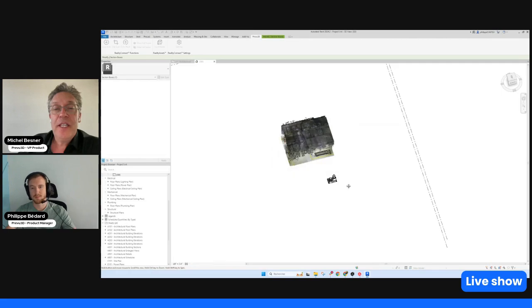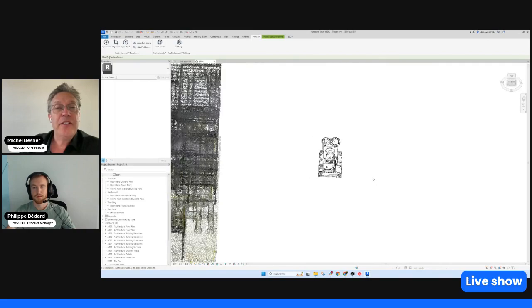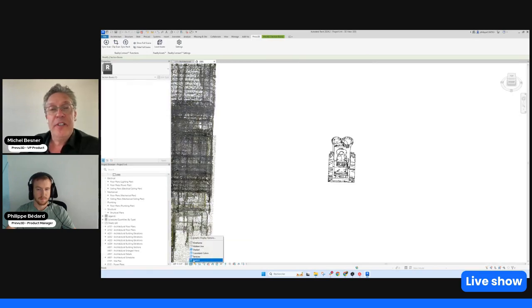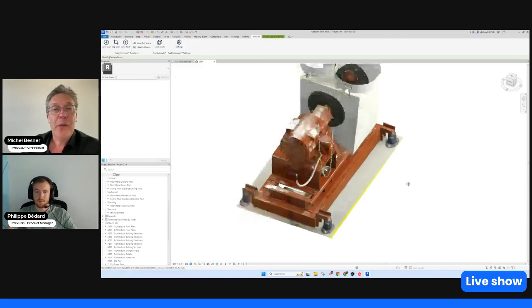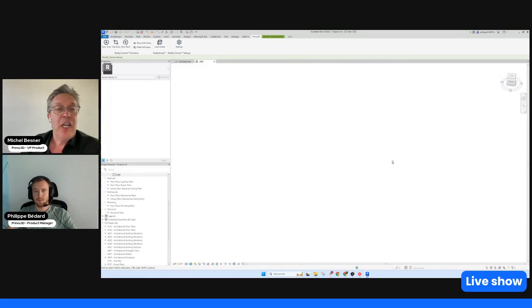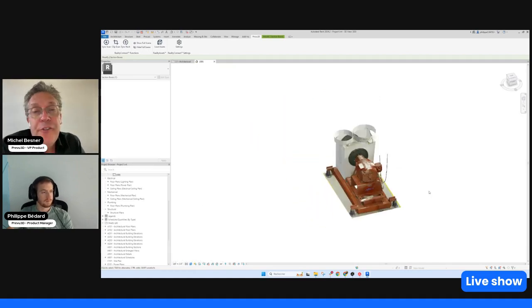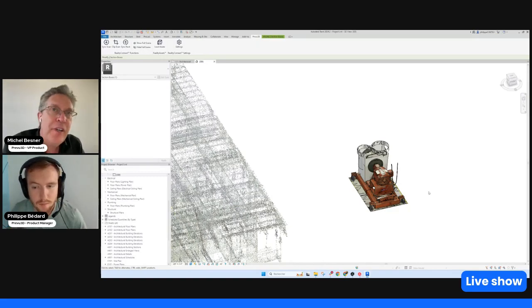I can use that as a contextual asset that I need as a reference, because there are certain things in my design project that are not moving, so some of the piping and the ducts still need to be there because they don't change, but I still need a reference as I'm doing my CAD model. Or I can use this as a CAD asset reference to do my back modeling. This is coming right now as a generic asset into the system, so you can even reuse that as an asset in the environment in Revit. But as you can see here, in a few seconds, we're able to move a pump between Preview and Revit without having to do a cumbersome filing, saving a file, loading a file, and back and forth.